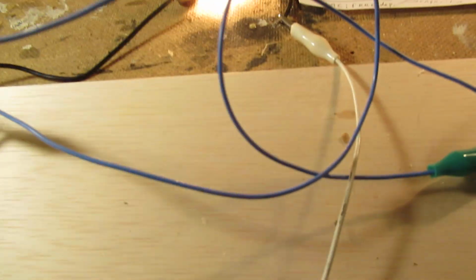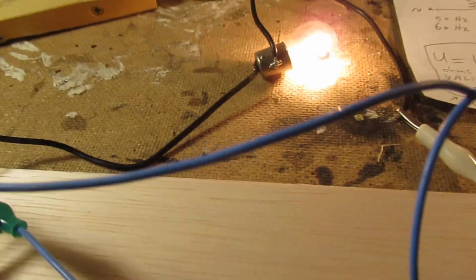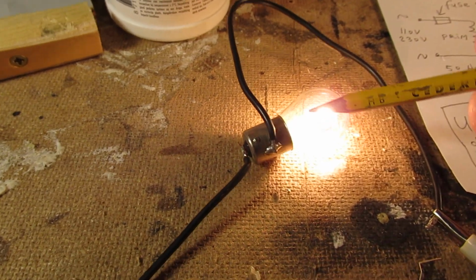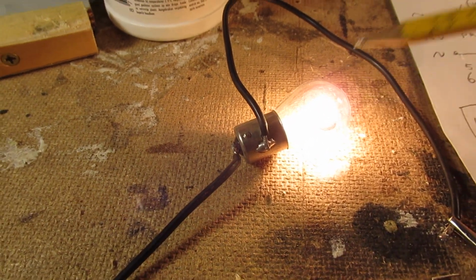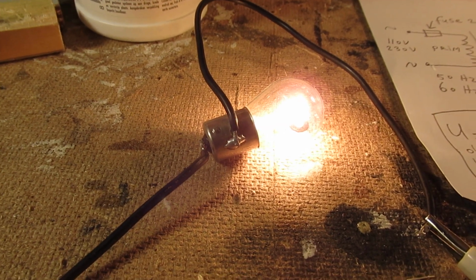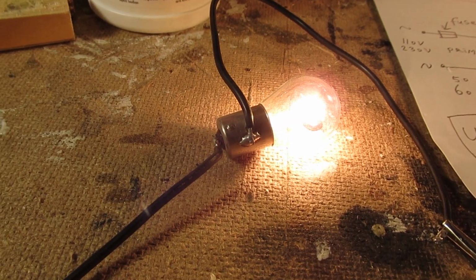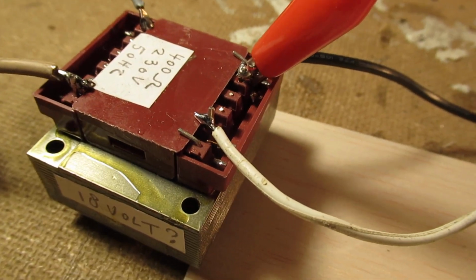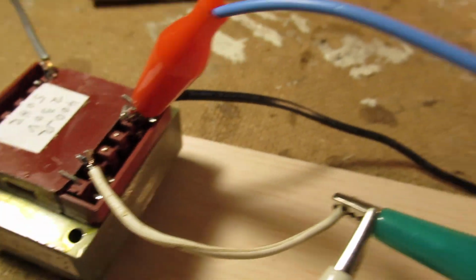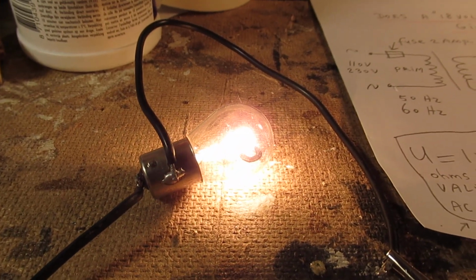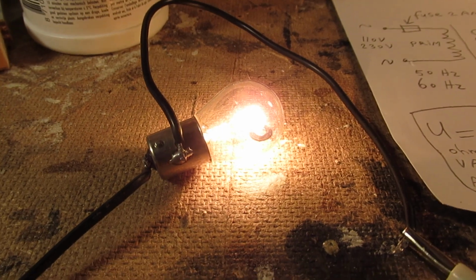When you want to do more experiments, you can search for a resistive load that makes the transformer give out exactly 18 volts AC. This is a heavy load. That's a good idea, then you know what the transformer can deliver.